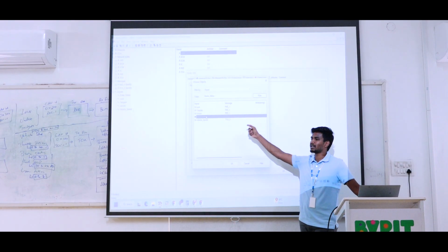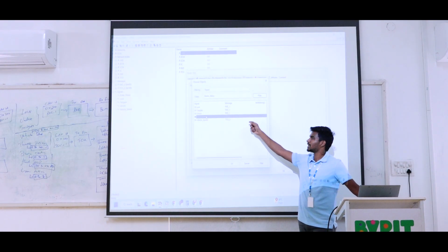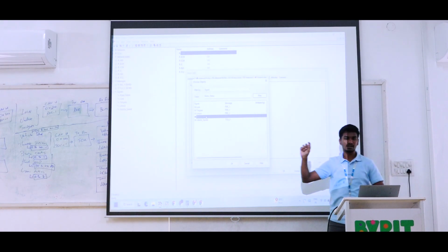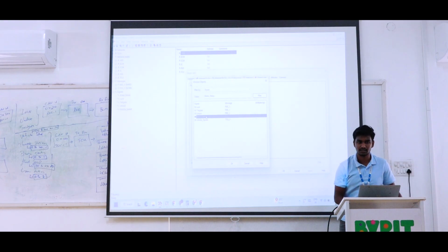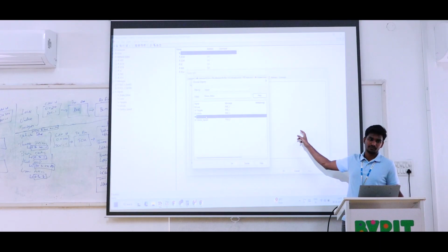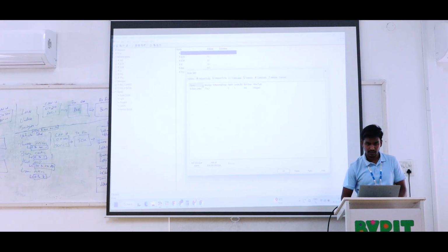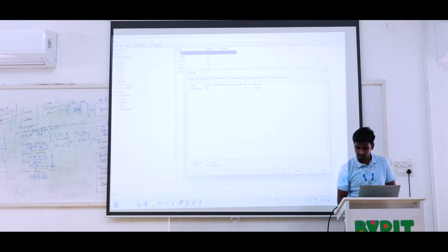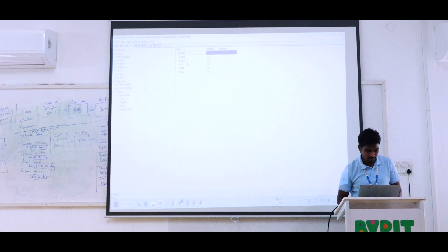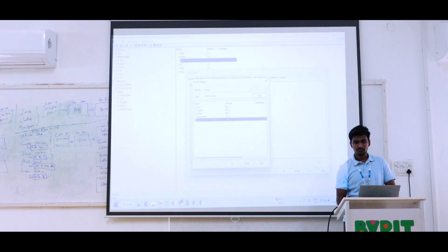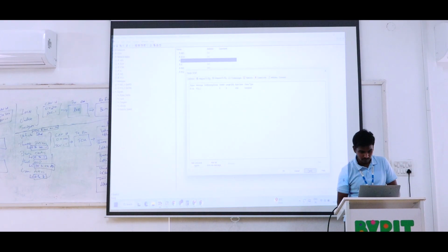The receiver just takes the ID of the message and accesses only the starting bit of the brake status, for example the 9th bit. So now it is accessing only the brake status. Next we can give it to the ECM, received only the vehicle speed. In the same way we can give it to the IC also.